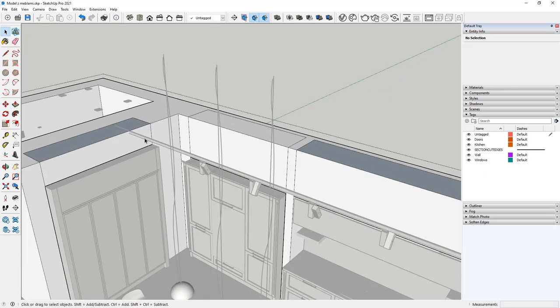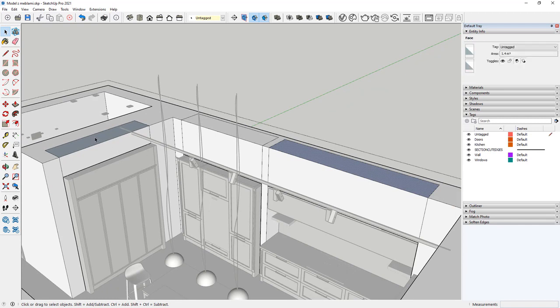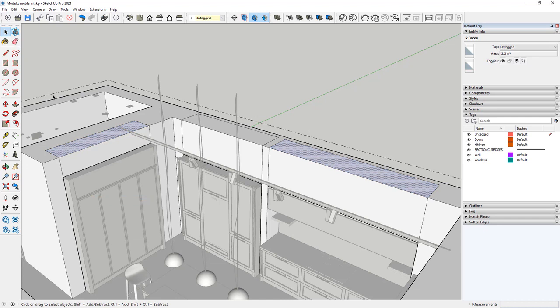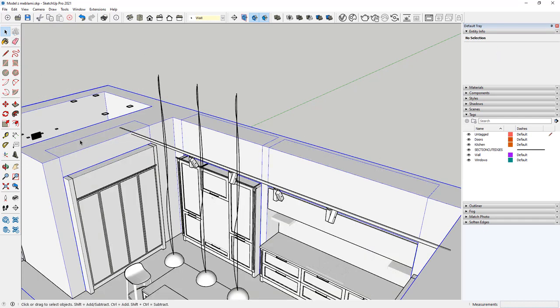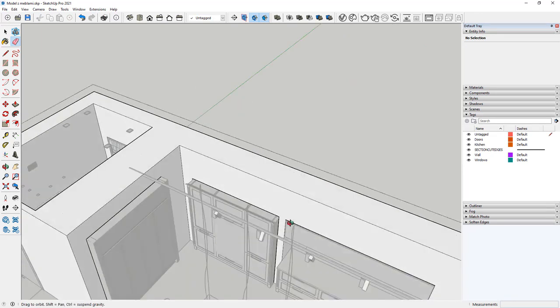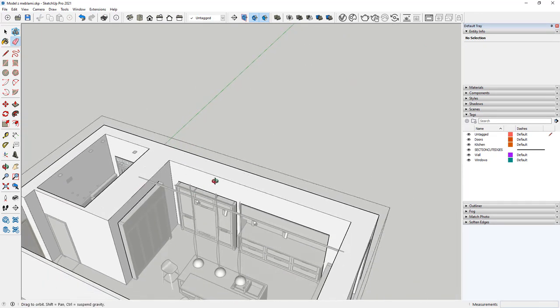Okay, the last thing, we need to reverse the faces, and of course we need to remove all the unused lines. Always try to do this because it will generate some issues sooner, so it is better to remember about this process at the earlier stage of your modeling part.